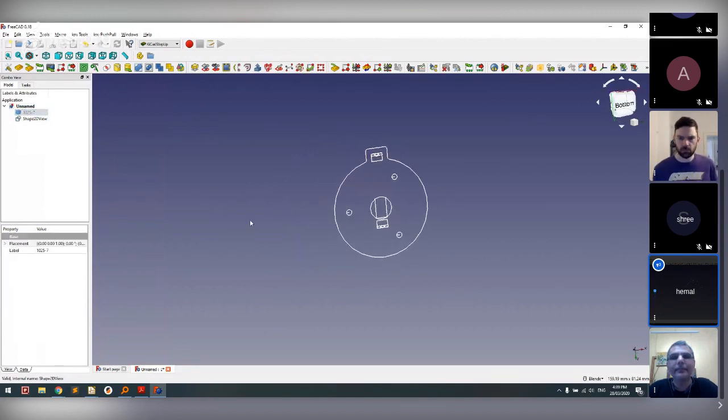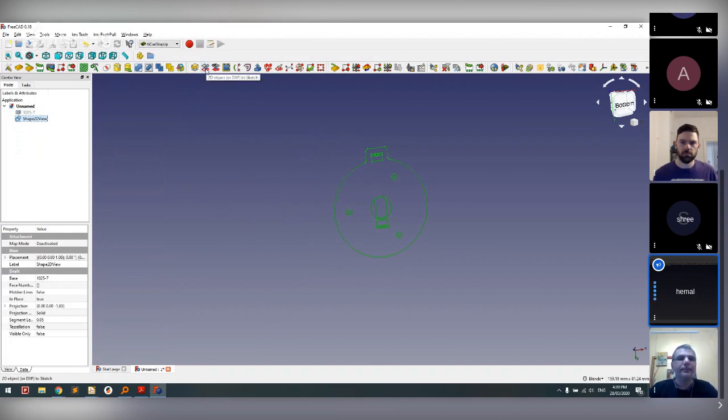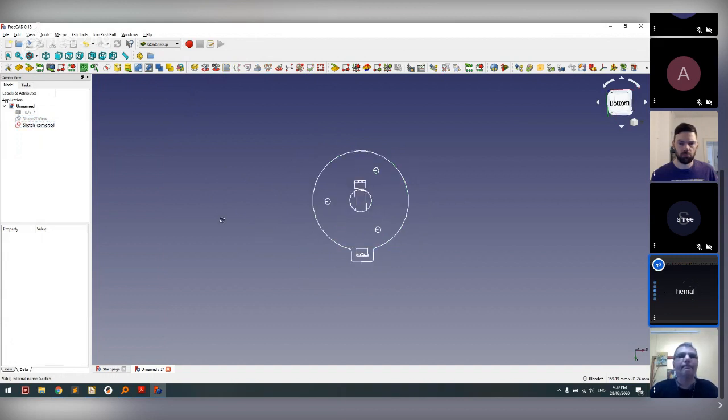So now we need to convert this into a footprint. What I did for this one is I only needed the silk layer. So I converted this into a silk layer and then I exported as a footprint. And the pads I did in KiCad from the datasheet information. So once you have the projection, you click here, and then you have to convert that object into a sketch. Once you click on this button, it is converted into a sketch. So pretty much right now, what I need is here.